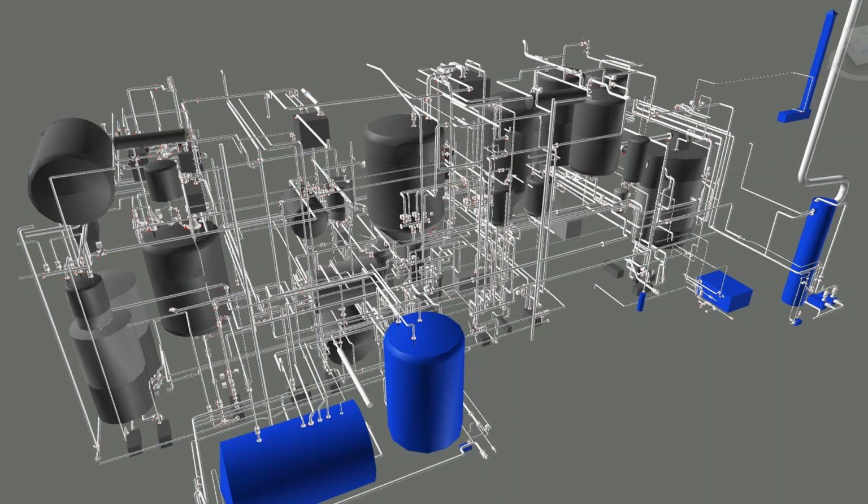Now this particular image is not the finished article, but it's halfway through the project. What we've done here, we've rendered the point cloud through Edgewise, exported it, brought it into Autodesk Plant 3D, and added all the extra bits, including pipe supports and flanges and valves. You can do this within Edgewise, but it's not something that we've particularly tested, because there were so many different specs going on within this project.